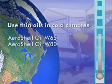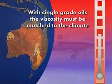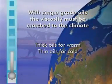But in colder climates, thick oils will flow too slowly when an engine is first started. In this instance, the oil should be changed for one with a lower viscosity. The key thing to remember is that with single-grade oils, the viscosity must be matched to the climate. Thick oils in warm climates, thin oils for cold.